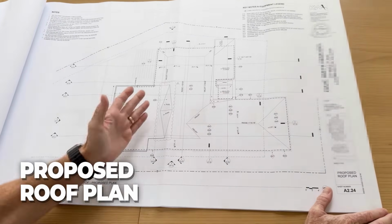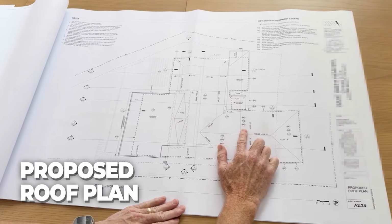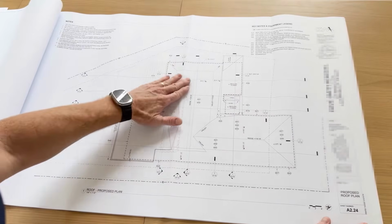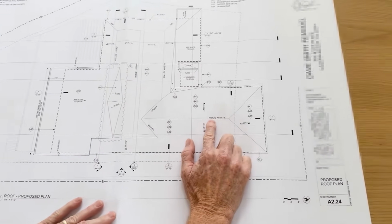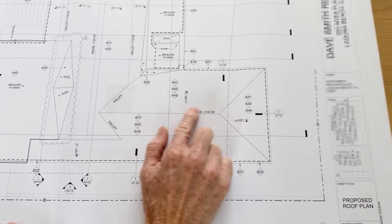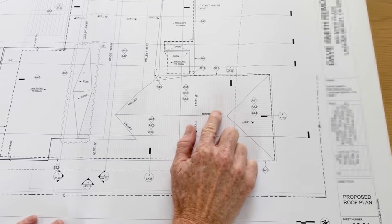Roof plan, guys, you can see it's just a lot more information. Again, follow the abbreviations. It's somewhat redundant as the other pages, but basically it's talking about how we're going to frame the roof. This number here is important. This is the architect telling us that the ridge, at the very top of the ridge there, is not allowed to be more than that number, okay?